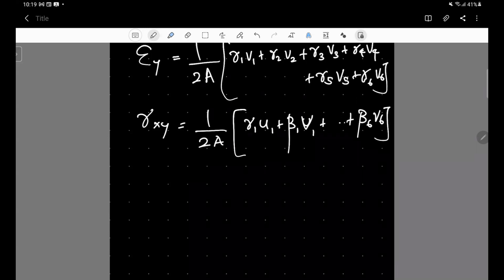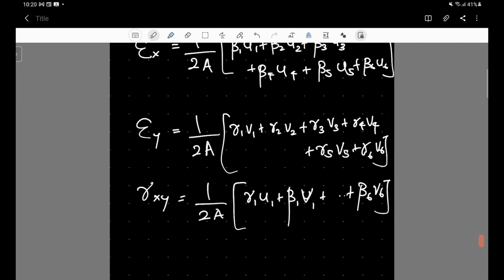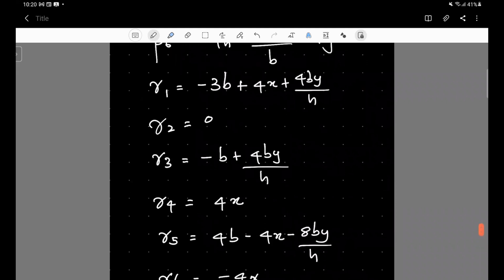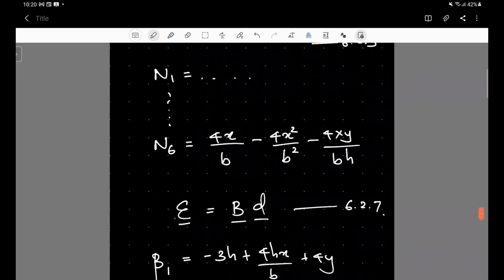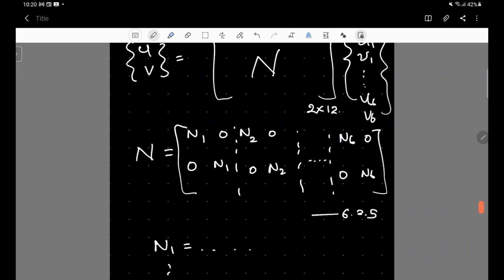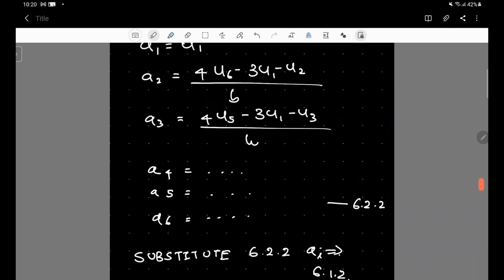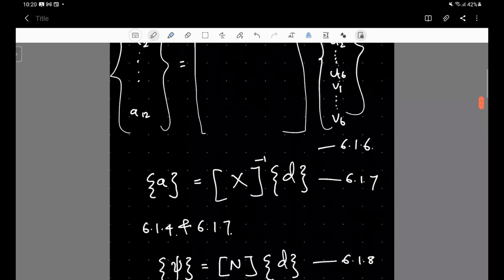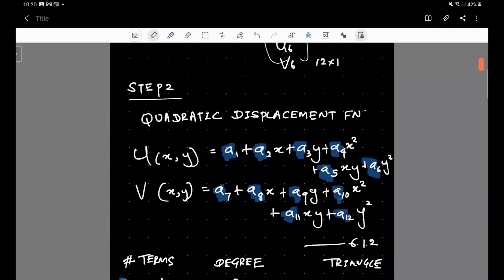So now the stiffness matrix for a thickness element can be obtained by substituting these equations for obtaining B. Since we already have the strain matrix and the D matrix, we can obtain the B matrix. And once we have this, we can substitute this B matrix and the constitutive matrix into this equation, the fundamental equation, and perform the integration.